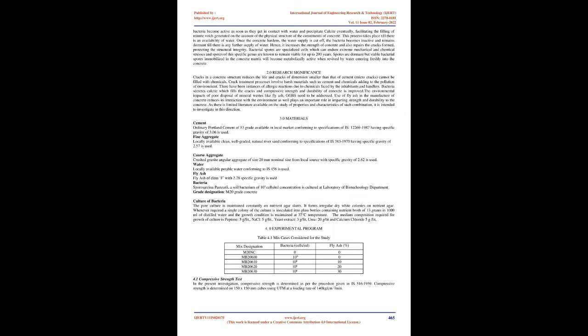Based on the results, the mix with a combination of 10^6 cells/ml bacteria and 20% fly ash, MB20620, has given optimum performance in terms of compressive strength, split tensile strength, strength loss, weight loss, and water absorption. Keywords: concrete, self-healing, bacteria, fly ash, MICP, strength, durability.